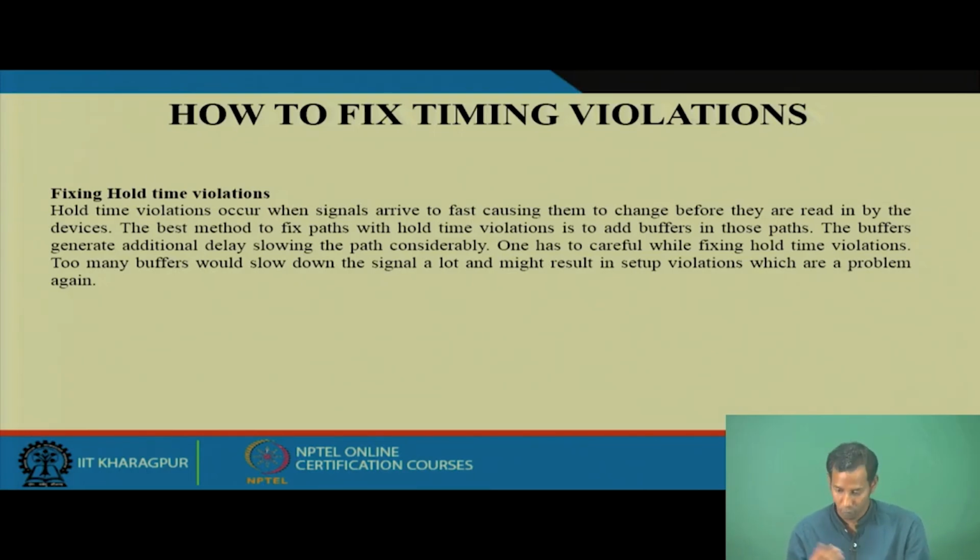So, what is the necessity of these buffers? These buffers generate additional delay, slowing the path considerably, and one has to be very careful while fixing the hold time violation, because adding these buffers again affects the clock time requirement. The cycle time will be more. So, you have to be careful when applying these techniques, and too many buffers would slow down the signals a lot and might result in a setup violation, which will be a problem again.